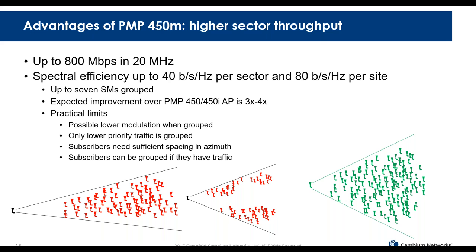Imagine, for example, we are communicating with 3 subscribers, where 2 have a lot of data to transfer, and the third one only has a short VoIP packet. So we form a group of 3, we start sending the data, but one of the 3 has a short communication while the others keep going. This is not the most efficient way of forming a group. We are better off selecting another subscriber that has a large amount of data to send so that we can keep using the symbols in the group to send more data.